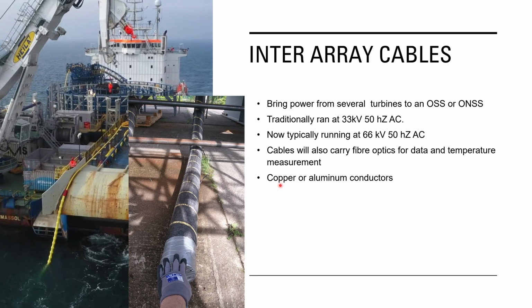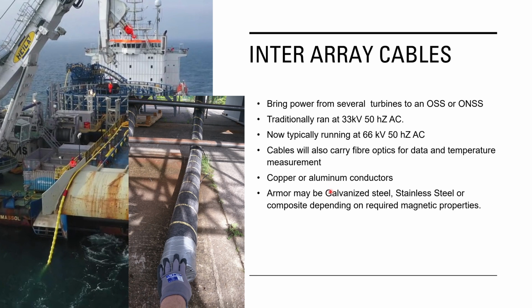The conductors can be copper or aluminium. I mean, in principle they could be any metal really, but copper and aluminium are good conductors, and aluminium is of course cheap. Now copper is a better conductor. You need more aluminium both by weight and volume to conduct an equivalent amount of electrons with the same losses, but because of the cost of copper recently, aluminium is increasingly being used.